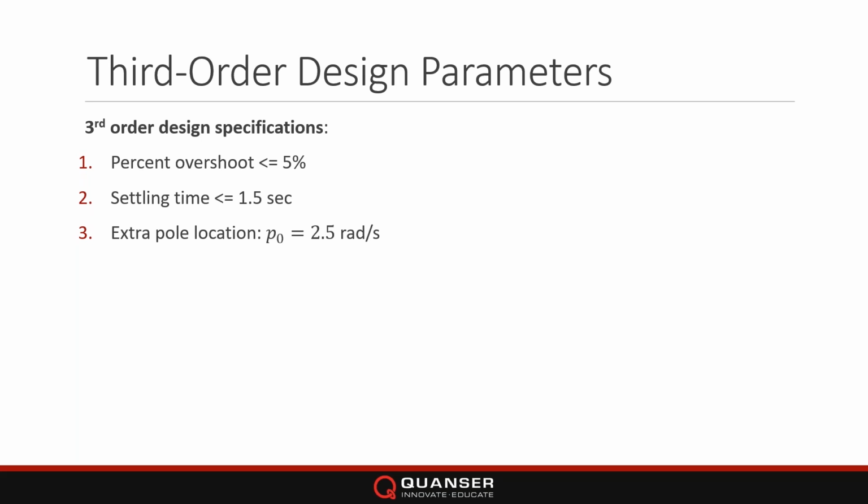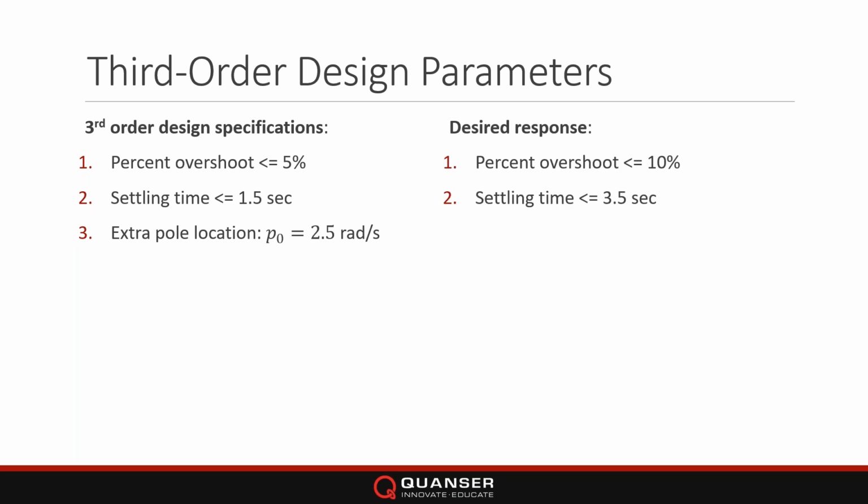The extra pole you can move around, right? So you can move it to 1.5, 2, 3, and you need to do that because it's iterative. You're not too sure where the dominant pole should be. So that's why you simulate everything prior and then you look at what your control effort is, and how does that affect your response, right? So that you can tune.